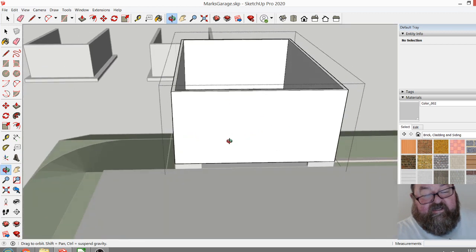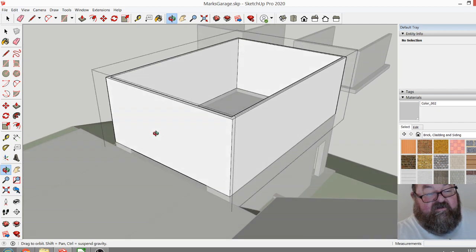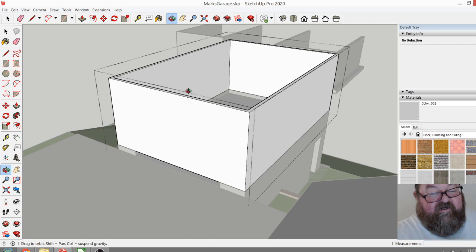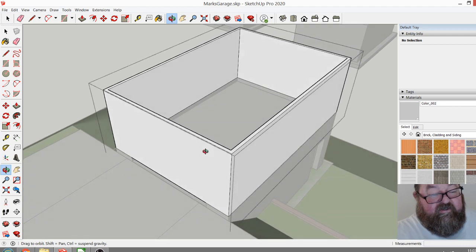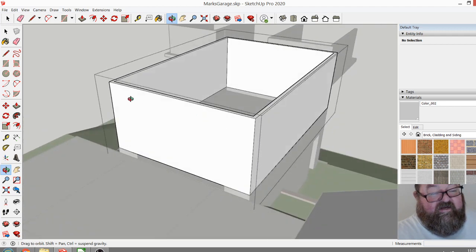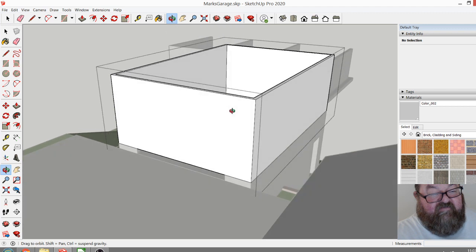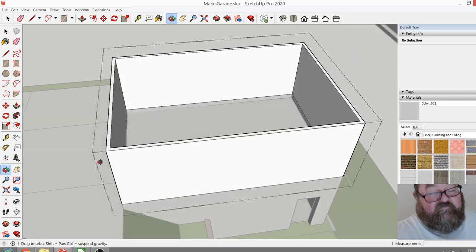But what you need is enough room. He wants an 8-foot tall door, which I applaud. I would never use anything but an 8-foot tall door. You need room for a header above. You really need at least a 9-foot wall to get an 8-foot door, because you want to have at least 12 inches of space for your LVLs for your door header up here.